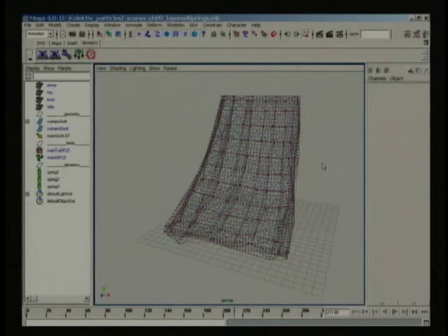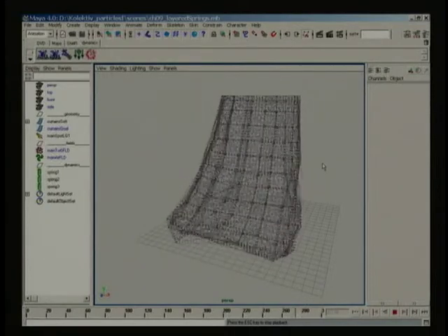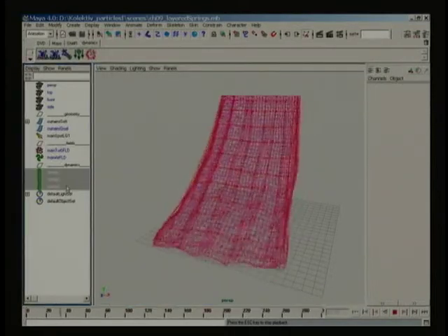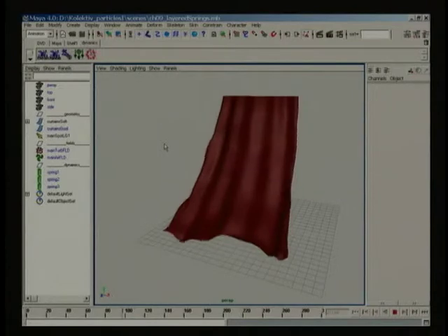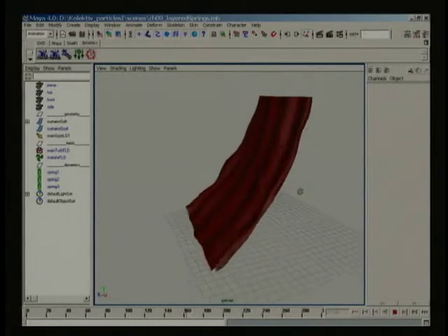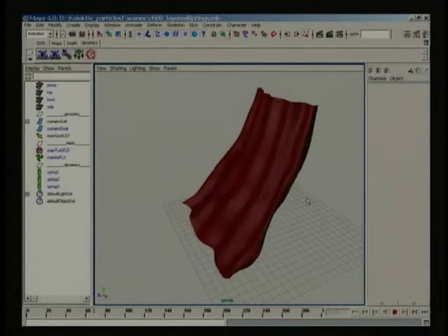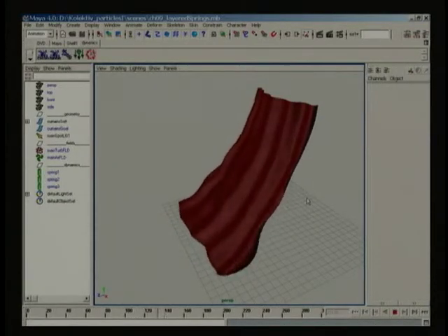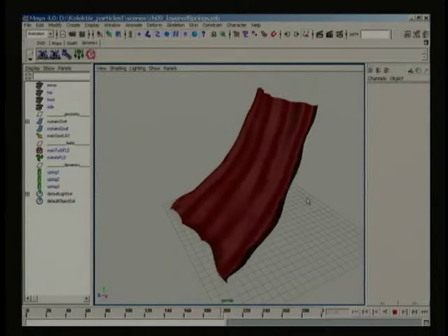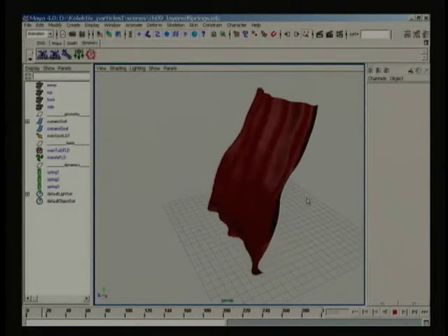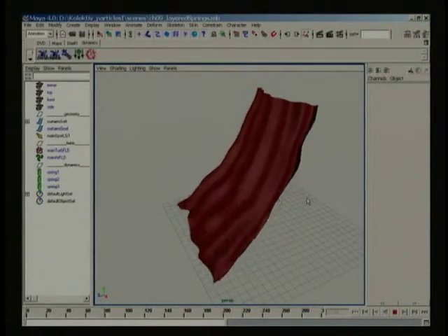You may need to execute this method several times with different settings, adding to the current spring object. This technique allows you to gradually decrease your min-max lengths until you have sufficient internal spring structure. Note that adding to existing springs created with wireframe walk lengths is not a good idea, as you want to control each of these objects individually rather than exert overall influence over your softbody.